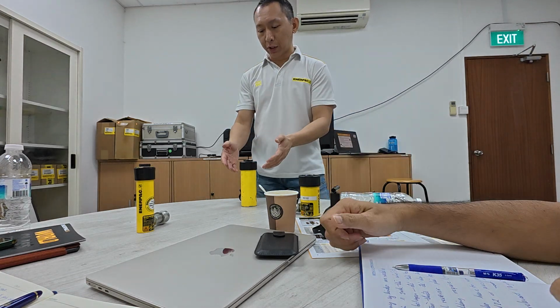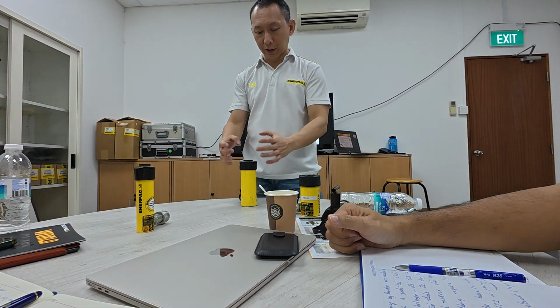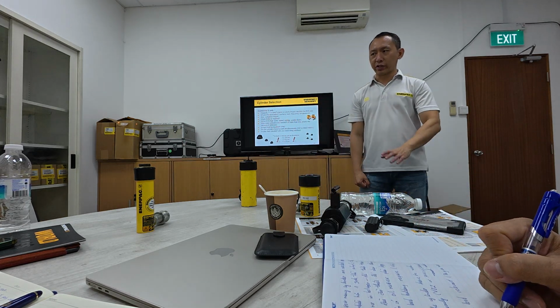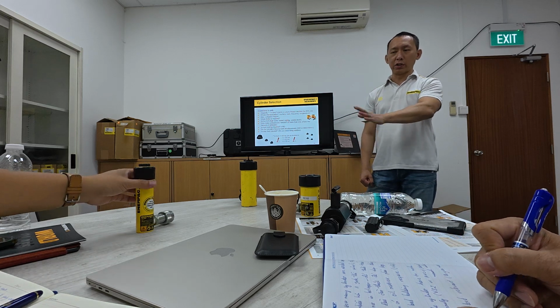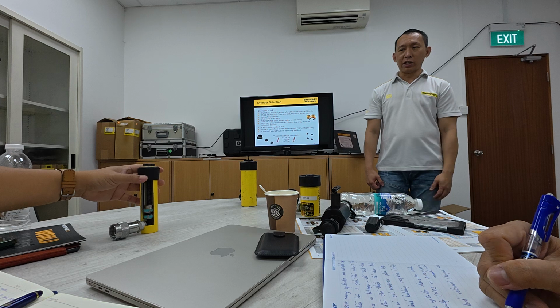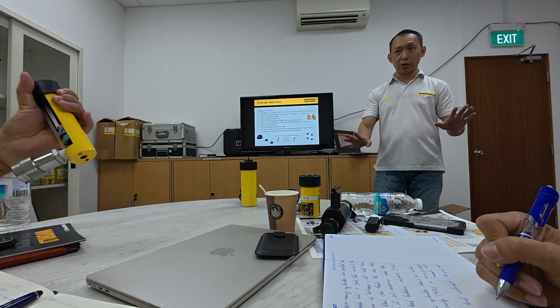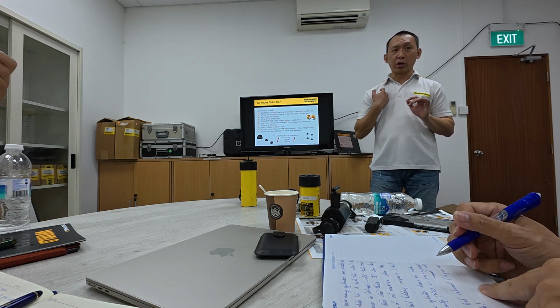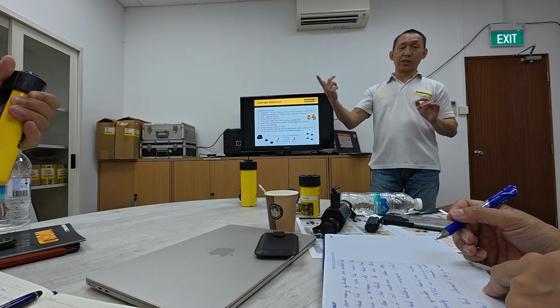Once you open up, the inside of the cylinder body is very clear, because with side load the plunger will rub against the side of the wall. Usually when that happens, the whole side of the wall is scratched. It's very obvious, you can see one clear scratch. That's definitely not a warranty. That's a misuse, and if the customer says it's not their fault, it's not possible. It's definitely on their side. It's not that we refuse to give warranty, but if we give warranty, we are admitting it's our quality issue, which is not, because this is customer misuse.